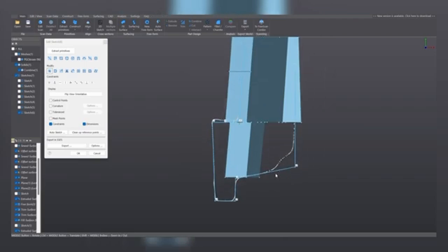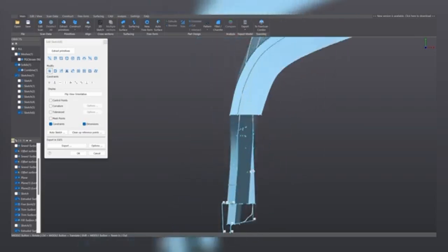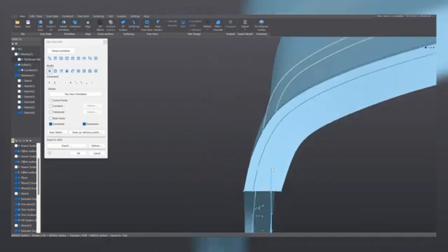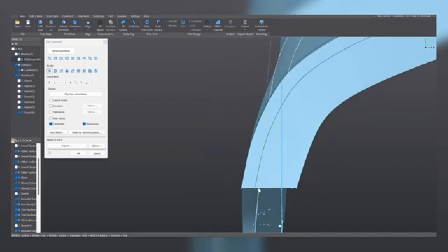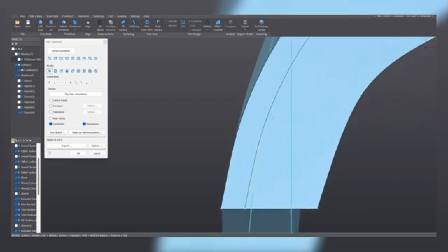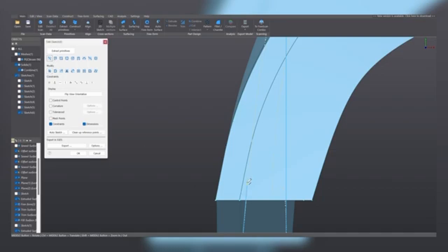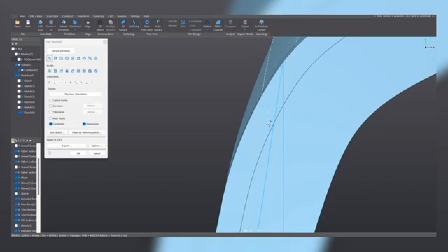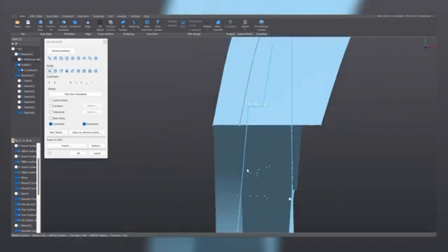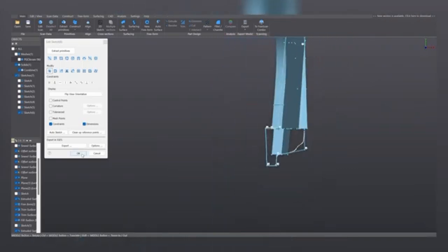Here, let's assume that we can ignore this deformed shape of the mesh. Now let's extend this line, making sure that it goes inside the shape of the body. And let's also extend this other one, but paying attention not to go beyond the geometry of the original object. So we are going to move a little bit to the inside and then connect the two endpoints. Here I can see that they appear orange, so let's make sure they are connected. Now this is a closed sketch.